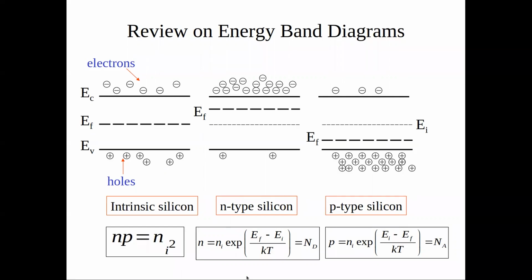Yes. Just quickly, could you maybe explain the Fermi level? Like, why does it move up or down depending on that? Well, it's really the point at which you have the equilibrium between the concentration of carriers in the conduction band and valence band. So if you just take the difference, this is where everything would be at steady state, without any charge flowing or any energy being dissipated.